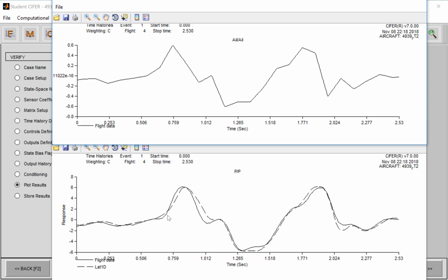So it's running a simulation, you're inputting into the simulation this, and you get this result, which matches closely in basically the amplitude, right? The peaks are of the same amplitude. It looks like it has lots of the same characteristics. Obviously, there are errors, but overall, from all the system identification I've seen, this is a good result. It looks like we've predicted fairly well the dynamics of the aircraft. You should be able to run this case for anything, so you can even run this for frequency sweeps, and you should see the same result.